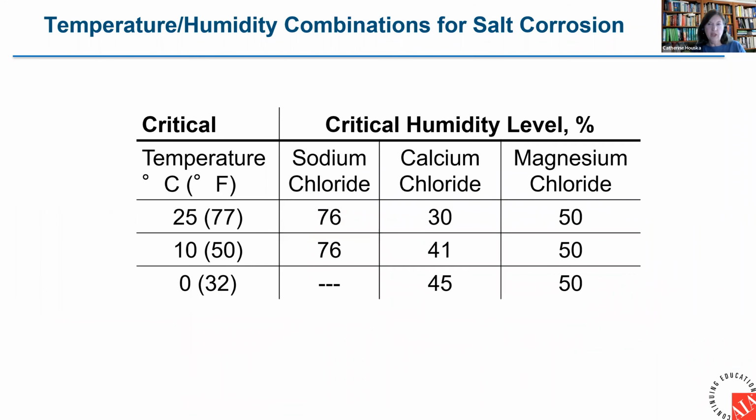And we've made a lot of changes in what we're using to de-ice. It used to be sodium chloride, rock salts. And when we used sodium chloride, until you reached a temperature of 50 degrees and 76% humidity, it couldn't pull moisture out of the air and create a salt slurry on the surface.